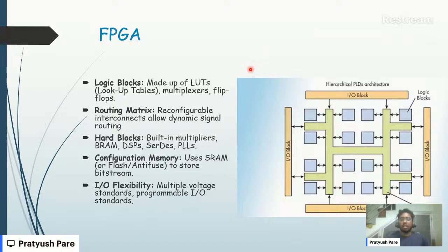Now in FPGA, we got logic blocks. Compare them to bricks. You have bricks, now what? You want something to stick the bricks together, right? They can't stand on their own. That's where the routing matrix is laid out. Like the green lines here, you can see. Using this routing matrix, we can use any of the blue logic blocks. Blue means the logic blocks.